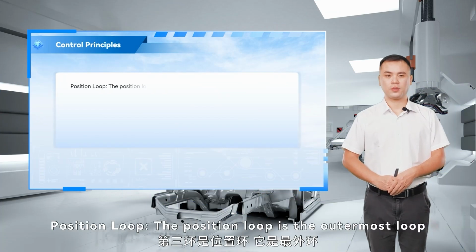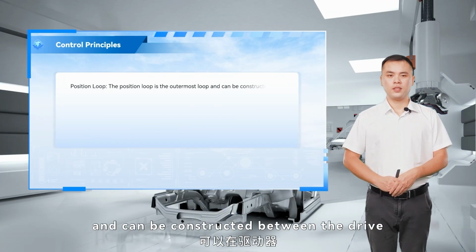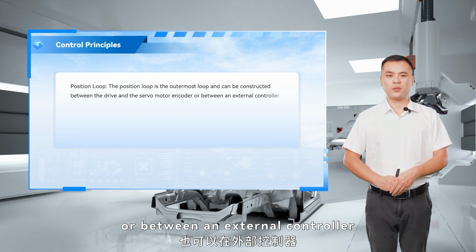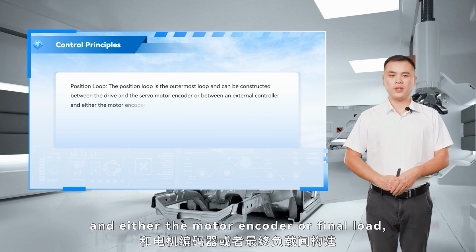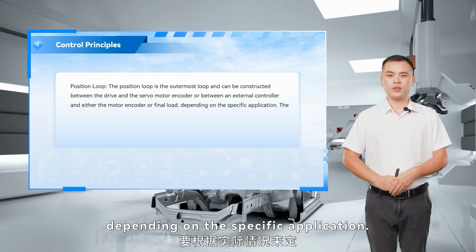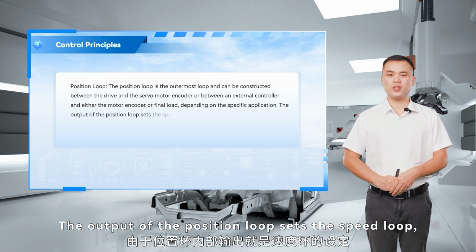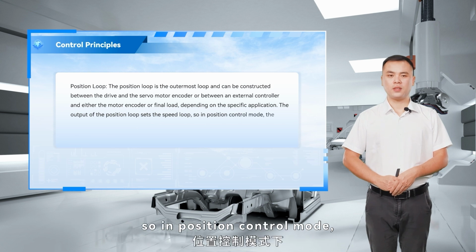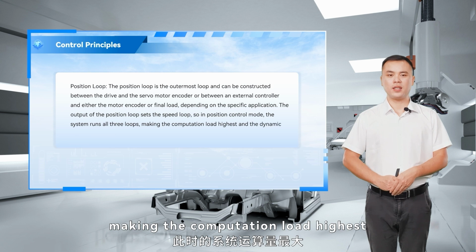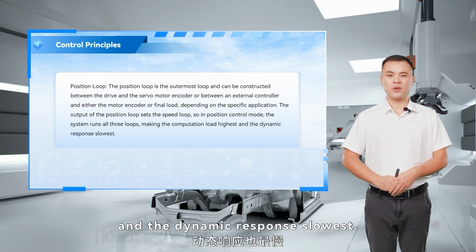Position loop. The position loop is the outermost loop and can be constructed between the drive and the servo motor encoder, or between an external controller, in either the motor encoder or final load, depending on the specific application. The output of the position loop sets the speed loop, so in position control mode, the system runs all 3 loops, making the computation load highest and the dynamic response slowest.